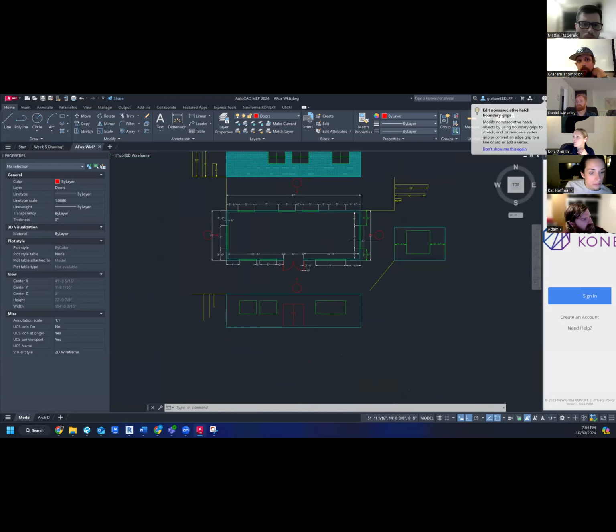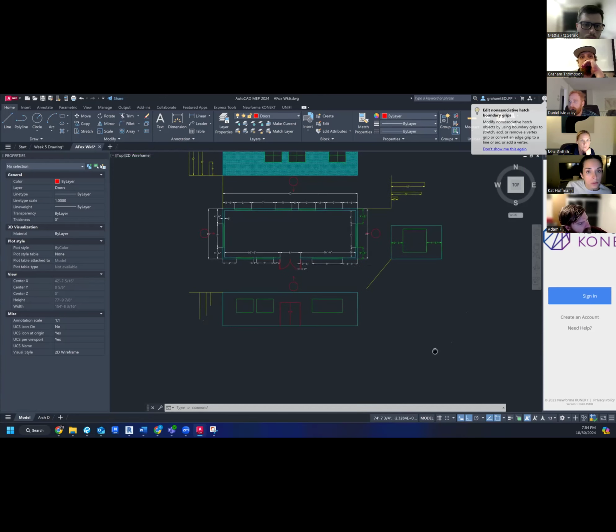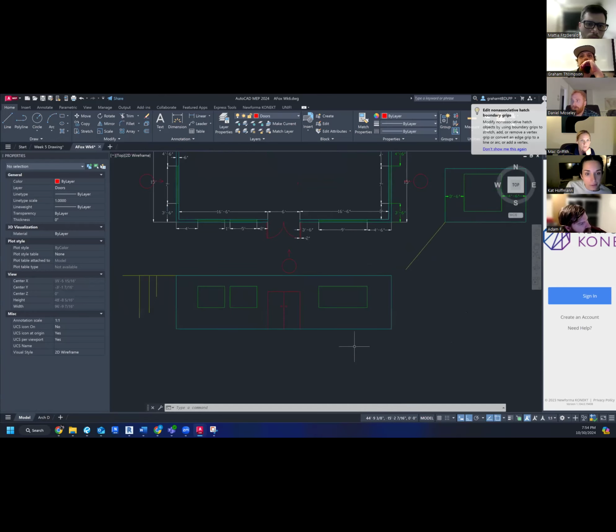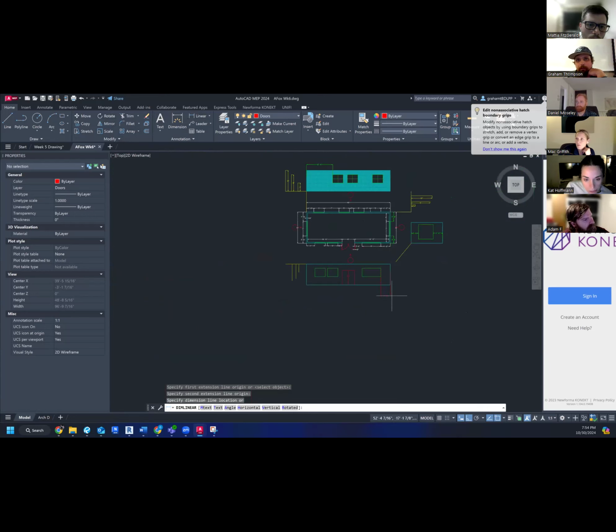But if you were to try to draw all these windows in by hand and place them in, it takes a lot longer than just drawing these story poles and drawing stuff out, especially when you have a lot of them, right? Well, and more detail too, right? Like flipping everything as a package as opposed to drawing it. But again, now to confirm, right? I'm coming here. All right, 4'6", and that lines up right with that 4'6", right?